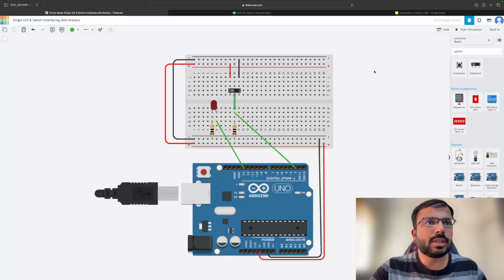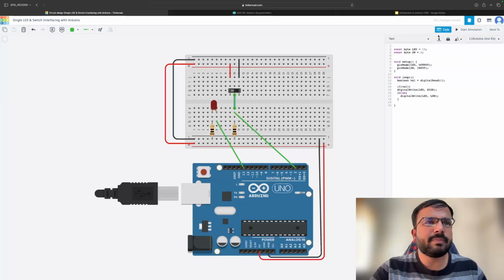So now this is the simple logic. Basically the difference is in connection, right? So here basically there is a single input pole, right? But it's a double throw, like either it can connect here or it can connect here. It was not like a push button, where only one side it connects, and if you remove it, it disconnects, right? So it is a single pole double throw switch, right? So similarly what I have done, right, take an LED which is connected to pin 13, right? This is a switch which is connected to pin 2 as an input.